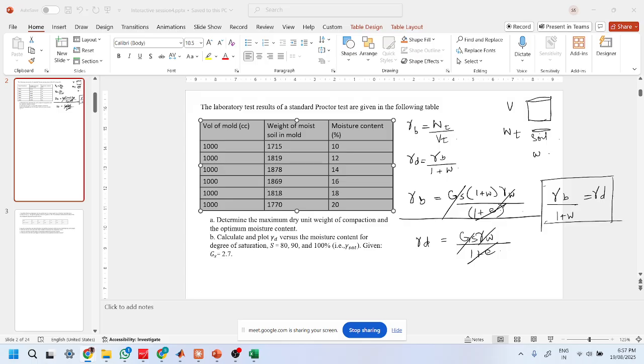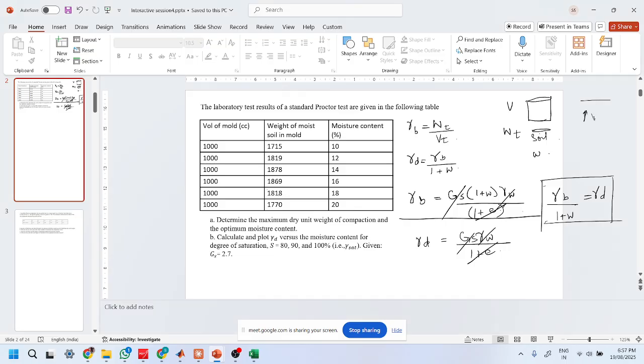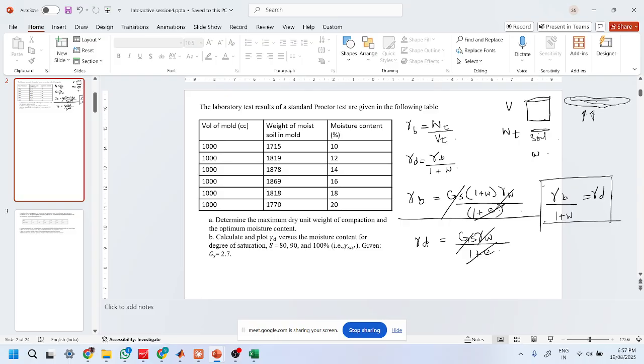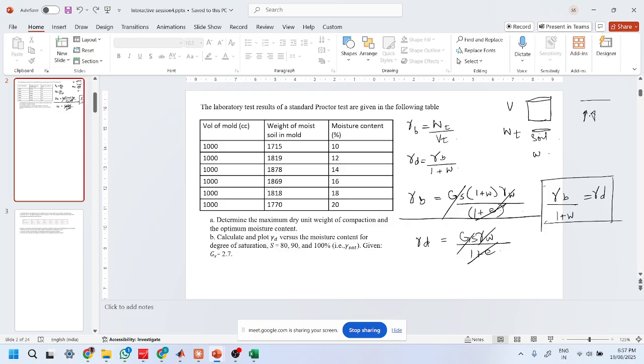In that case, if there is a dynamic load or a hydraulic head causing the water to move upwards so that the effective stress of the soil is nullified, you will get quicksand. So it's not a type of soil, but a condition that occurs when sandy soil is in a dynamic, saturated condition.